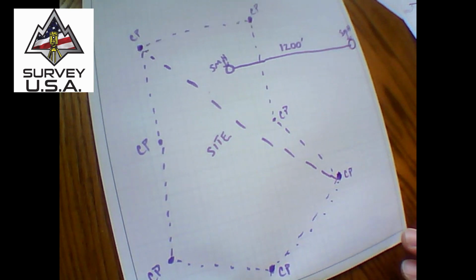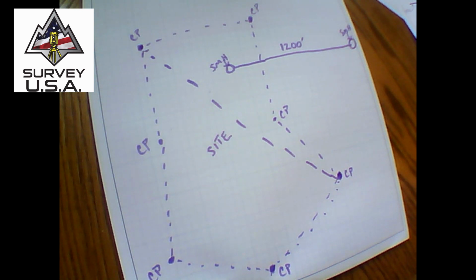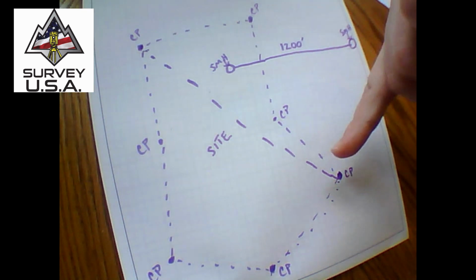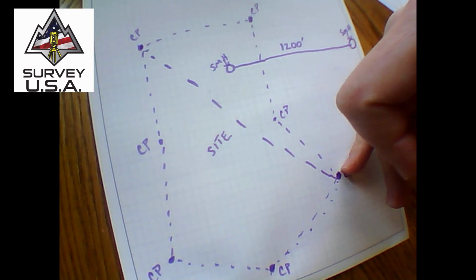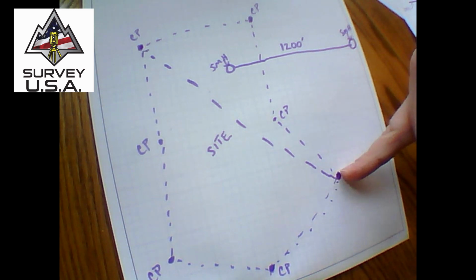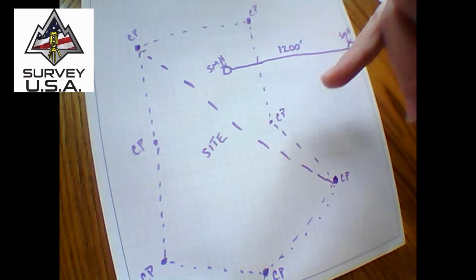Okay, so with the vertical calibration stuff, what we're looking for, number 1, select geoid/inclined plane. That's the selection in Trimble anyway. Like I said, I don't know about Leica or other technology or equipment, but that's what you're going to want. Geoid/inclined plane. Now, as far as that goes, I use 1 point, like I said. I'll calibrate to this guy vertically. Boom, I've checked every other one.